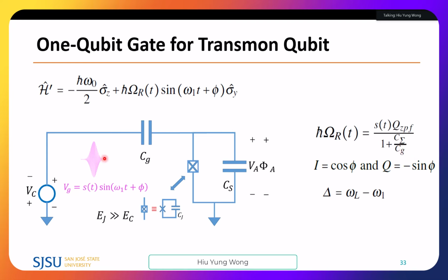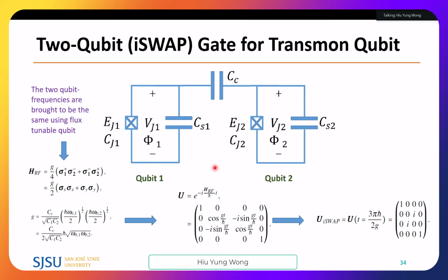So that's why I say circuit designers and microwave engineers control 90% of a superconducting or any quantum computer, because this is just a boring qubit and you are sending this pulse to it. And you can imagine any error you make in the arbitrary waveform generator, mixer, or local oscillator, phase noise are going to affect the quantum computing result.